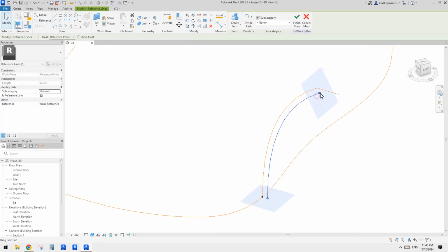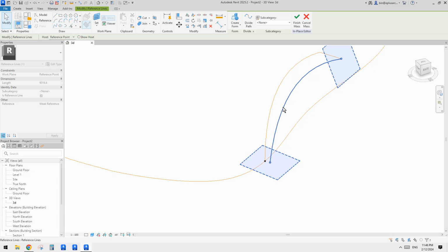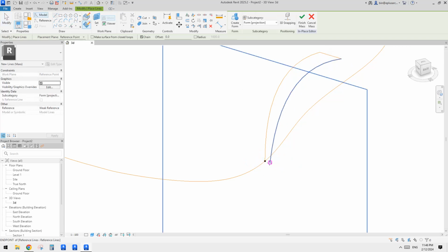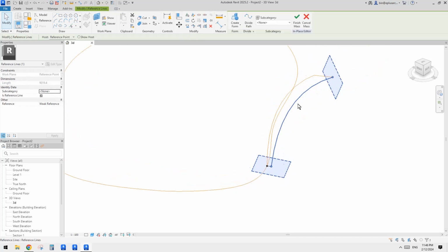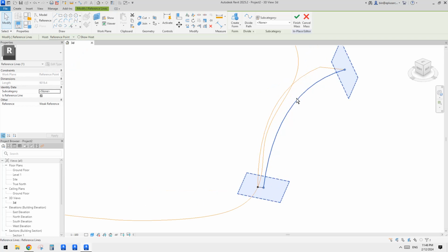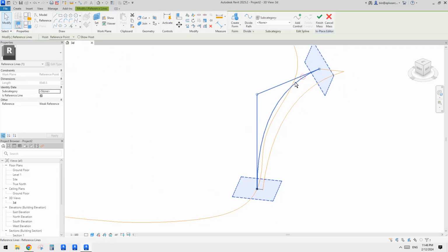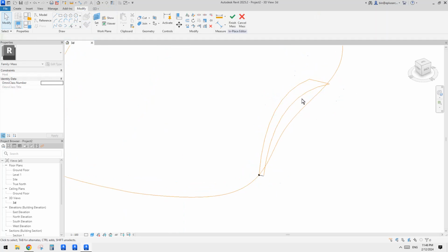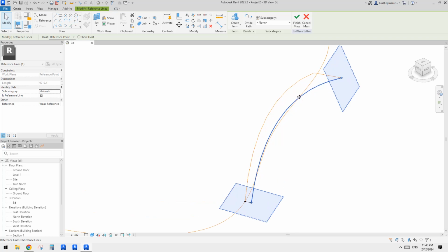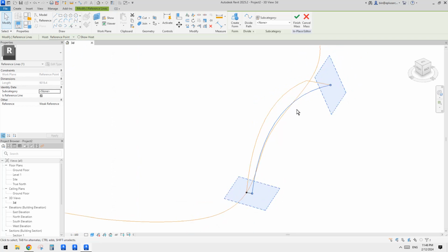And then we can probably drag this to this end, and then we can just do this. So just remember, because we used offset to create this one, we won't be able to adjust this by that point. See this one, this is spline, we have this point we can adjust, right? But if you use offset to create this one from this spline, you won't be able to adjust this shape.